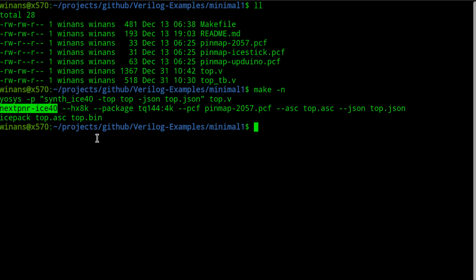One great example is, and we'll write one maybe and have a look-see at it, if you just put an AND gate in the FPGA and nothing else, it'll need a LUT to do that function. If you take that output of that AND gate and you don't connect it to anything, it'll figure out that that function doesn't accomplish any useful side effects and remove it from your design. And you can actually count the number of LUTs and stuff like that. When this compiler runs, it prints out all sorts of stuff. And you can actually see what number of resources are ultimately used, okay?